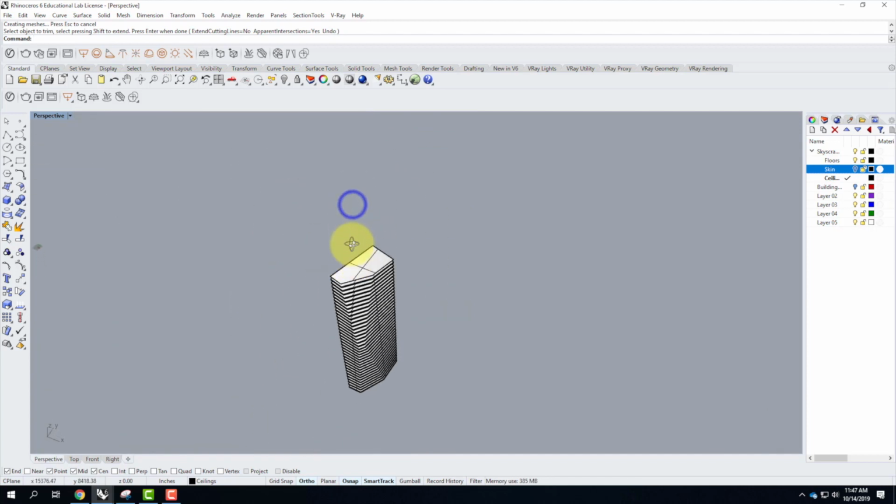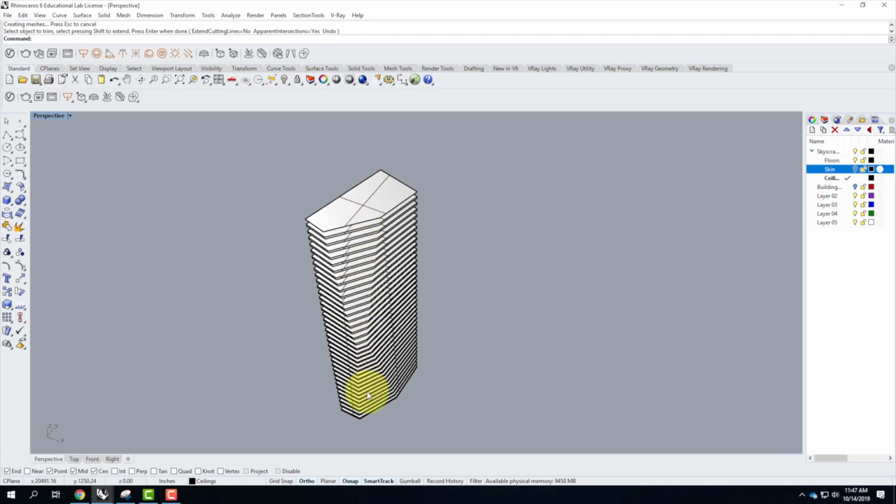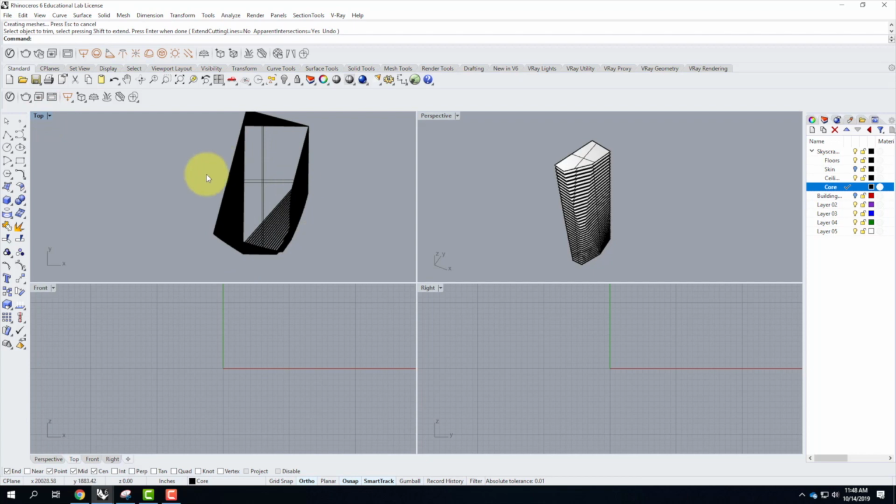So the next piece of this would be to actually punch an elevator core through the building. So the elevator cores tend to be straight unless you have a really fancy elevator that goes on a diagonal or something. So we're going to go ahead and create that part. So let me, using the skyscraper layer, I'll create a new sub-layer for core. I'll make that active.